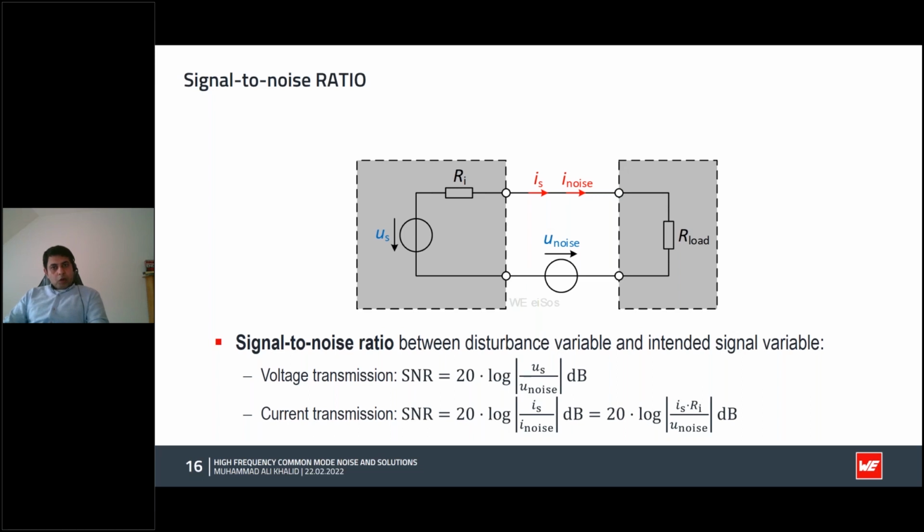Here is a small background on signal to noise ratio before we jump into antenna desense. It is important to talk about SNR, or signal to noise ratio, because it is the reason why we see problems in communication due to the introduction of noise. The higher noise leads to lower SNR levels, which can result in antenna desense.